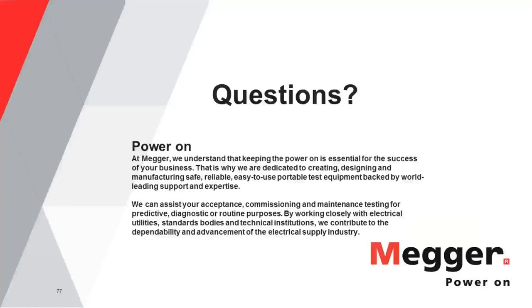What you want to keep in mind is that these assigned values are arbitrary, generally done by something like committee. They're not rigidly scientific. An example I can cite is that the phone companies have settled on 100 megohms for installation of what they call POTS, plain old telephone service. If you're the technician running these lines, you've been told they have to be 100 megohms. Now, does that mean that a 99 megohm line or a 95 megohm line is no good?